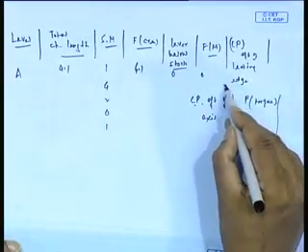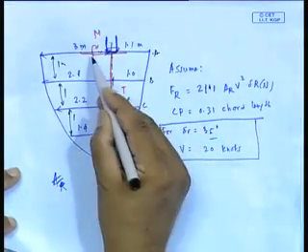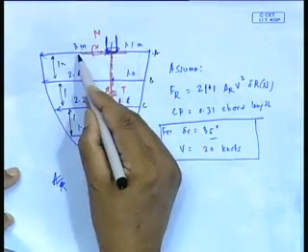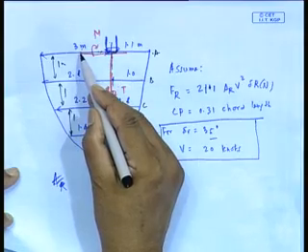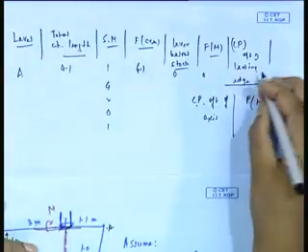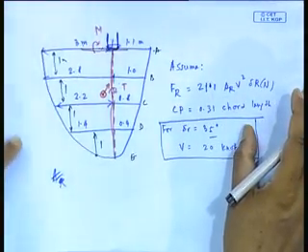Now, here Cp aft of leading edge, okay. From here aft, how much is it supposed to be? 0.31 times 4.1, okay. That will be 1.27. What I am trying to say is that you have to do this point by point.